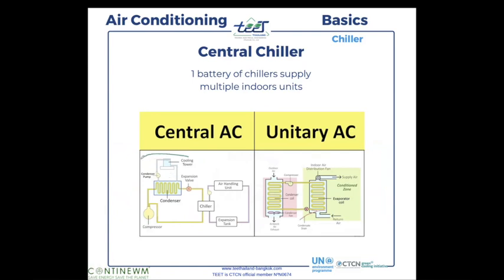So here we are zooming on this area, okay? We are talking about the cooling tower. Basically it has the same function as the compressor of a split type system, but instead of having the air outside going through the condenser coil, we have water, and this water has to be cooled because we work in a closed loop, okay? We don't use water from the city to cool the condenser because it would waste so much water. So we use the water to cool the condenser down, and we have to cool the water.